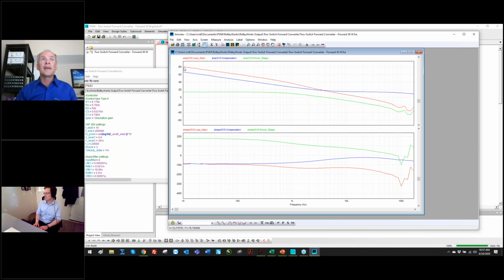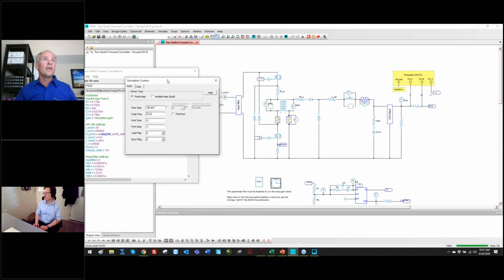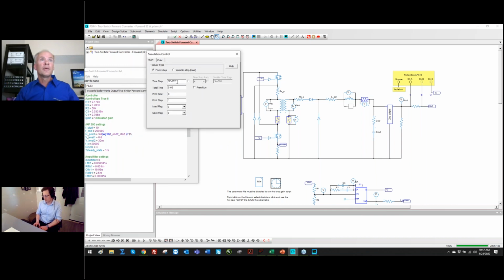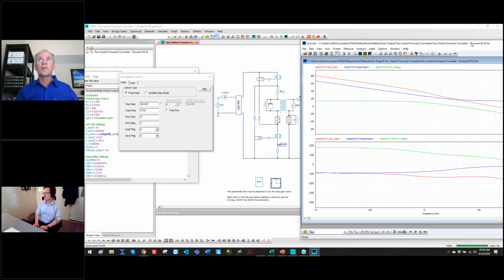Getting 80 dB of gain in this loop, a really clean sweep, which is almost magic to me, Albert, how you're doing this actually. But I'm shocked at how clean this is here in these very high gain values. And somebody asked a pre-question about the time step we're using, and it's not that fine. This is 0.2 microseconds is the time step. We're not trying to do a variable time step here. It slows things down a bit depending on how we set up the parameters. But it turns out you don't have to be that critical when generating the sweep responses.